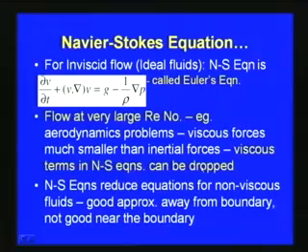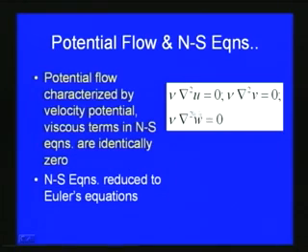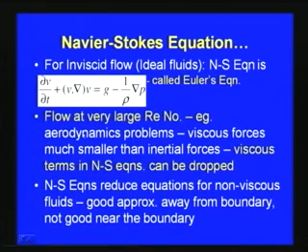And for inviscid flow, that means in the case of ideal fluid flow, the general form of the Euler's equation is del V by del t plus V dot del V is equal to g minus 1 by rho del P. This form of the equation we have already seen. Here, as shown in the previous slide, the viscous terms become 0 for potential flow, and then we get the Euler's equation.